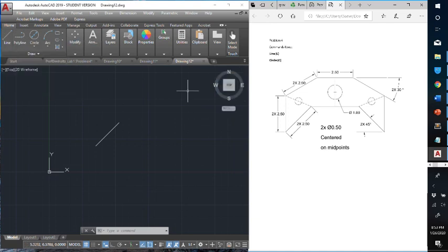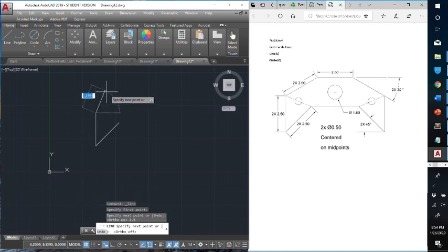All right, so continuing on, we're going to move up because we've drawn from here to here. We're going to move up by 2.5. So now I could turn ortho mode back on if I want, or I could just put in the exact angle. So 2.5 and turn ortho off. And now we want to go up at 2.5, hit tab. We want to put in an angle.